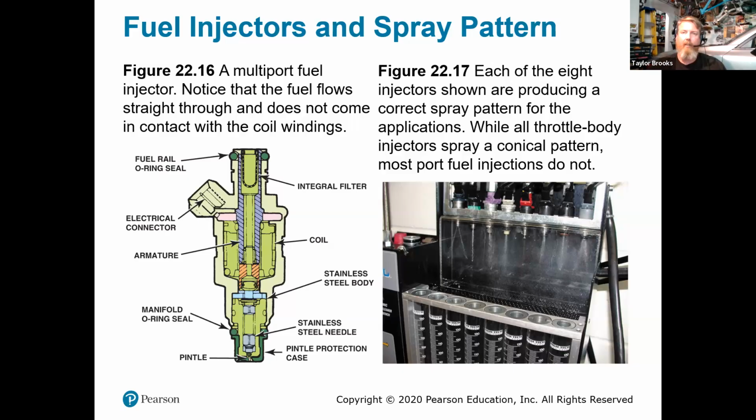So it is a good idea, if you've had any type of catastrophic engine failure, or if you have an engine with high mileage and you suspect drivability issues, to send your injectors out for flow testing. I've done this a couple times. I cannot recommend it enough. There's a company called RC Fuel Injection, in Montclair or somewhere in LA County, that can very quickly clean, test, and verify your fuel injectors.